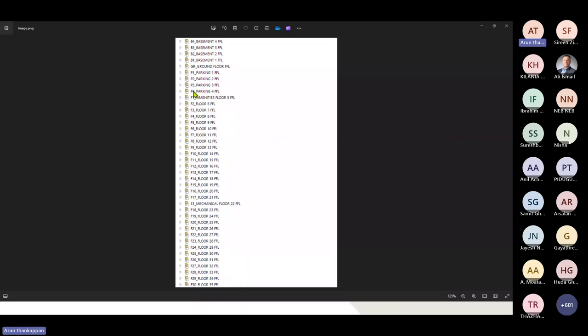After P4 you have to start from F1, but if it's not a floor, then you can write amenity. If there is an amenity level, you can write amenity, then level 5, then again F2, then floor 6. You can follow that in your 2D drawings, and make sure these are made based on the standard in the standard code book, the standard PDF file.